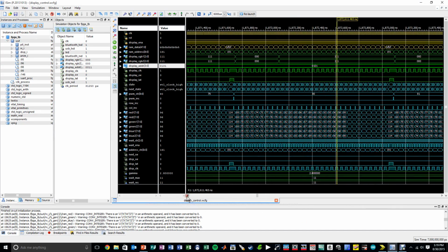So now we can see, if you count here, this is 32 clock cycles, because one row has 32 LEDs, so we write 32 values. Each gets clocked in with the clock signal, and you can see the first 7 or 8 pixels of the matrix are currently turned off for that row, and the remaining roughly 24 LEDs in that row are turned on. And once we've completely finished writing the data for that row into the LED matrix, we trigger the display latch, which loads that data into the actual LED drivers and actually turns the LEDs on or off.